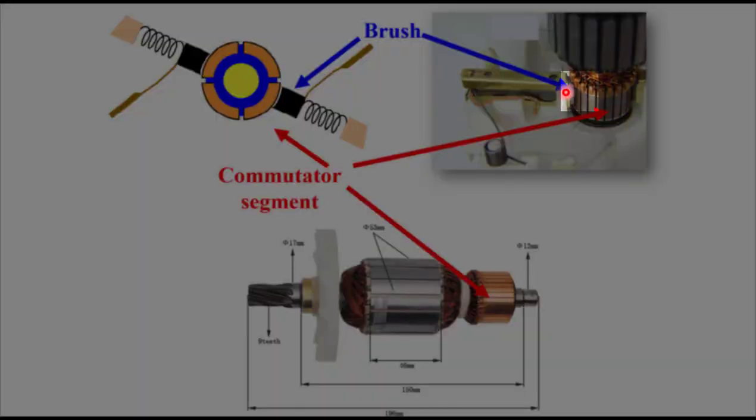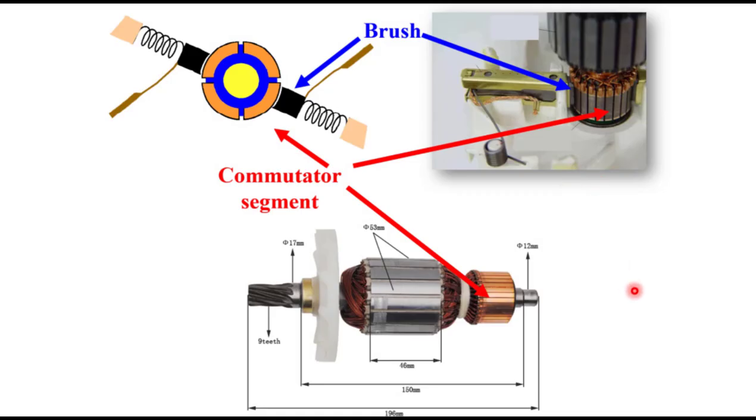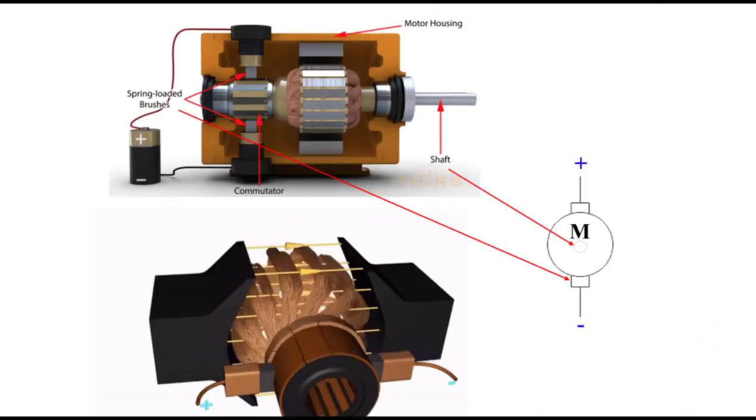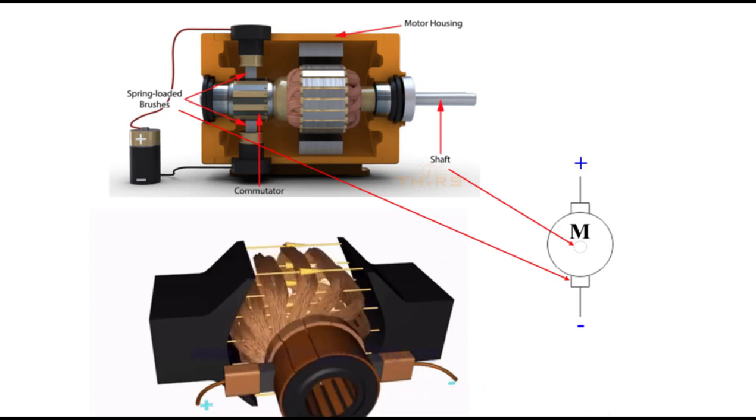You can see the brush here, the lead that's coming onto the brush, the spring maintaining constant tension on the brush. You see the shaft that runs through the motor. This particular piece here serves as a fan. As it rotates, it provides airflow across the motor for cooling. Another example how real pieces relate to the schematic symbols and in motion.